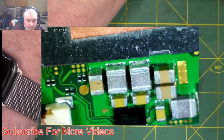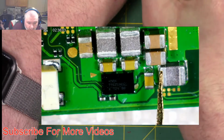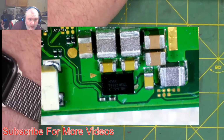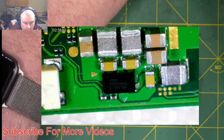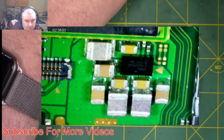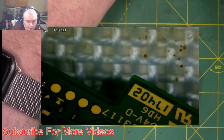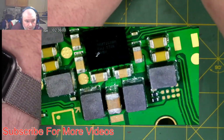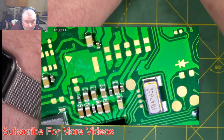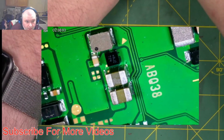And then down here by this Maxim IC, this power management IC, there are inductors right here, here, and here, and they are common to be seen. That's how I identify power ICs and power rails, because here is another Maxim chip that has 3 more inductors on it. And if you look on the back, here is another power IC, another Maxim IC that has 1, 2, 3, 4, 5 inductors on it. So if you want to find where your power in is in your circuit, look for the inductors.